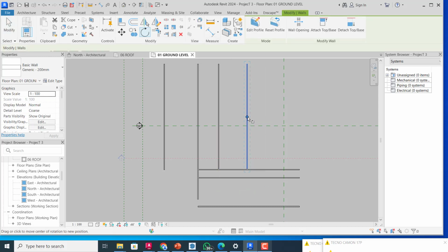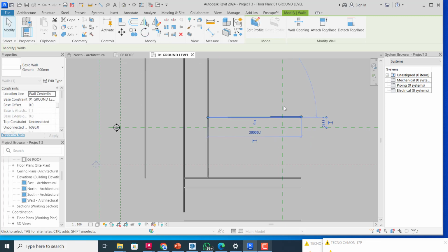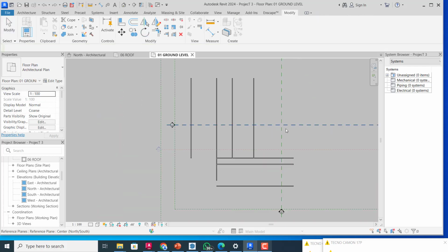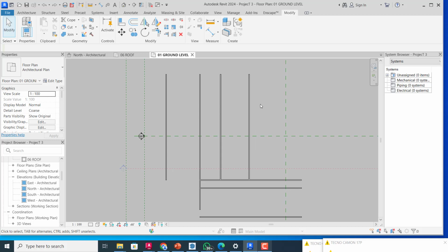Once you click on rotate, you can pick that point where you want to rotate from. If I click that point, I will select this. This is at angle 180, so I can just move. As I'm moving my hand, you can see those dashed lines showing me the direction where this is going to rotate to. And if I want to rotate this to this angle, 90, if I click on this, you can see that it has been rotated. So similarly, that is basically how to do it for all of them. To undo a particular command, you can just type Ctrl Z to bring you back.